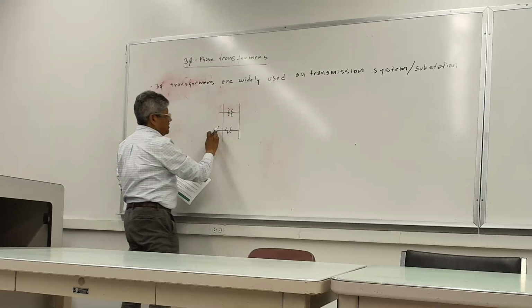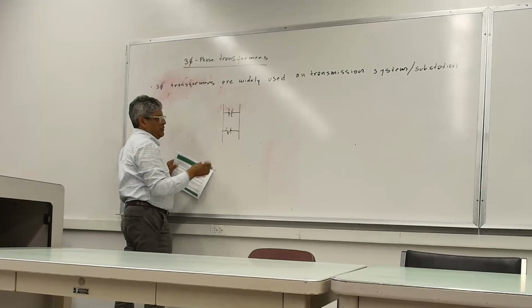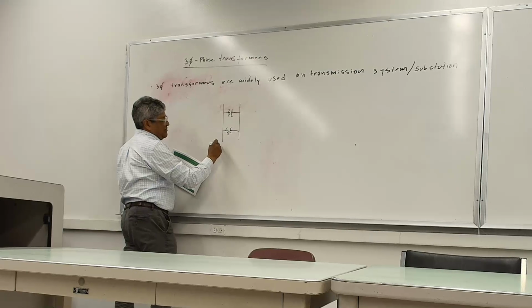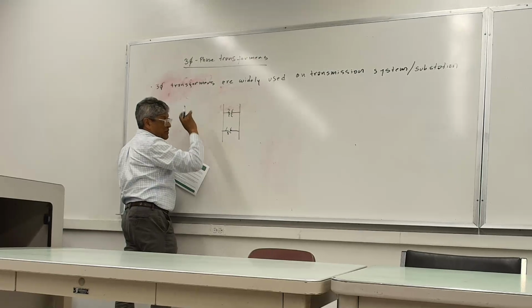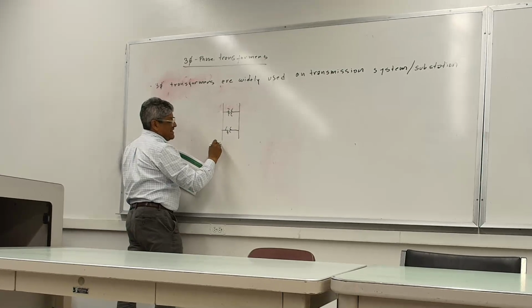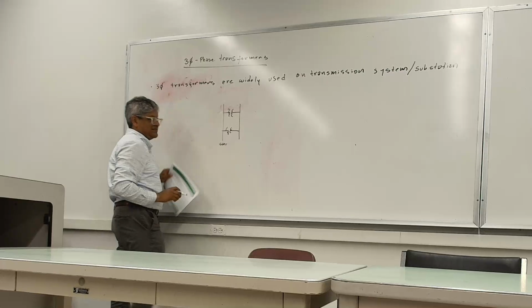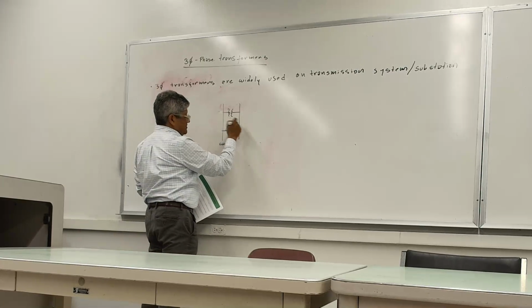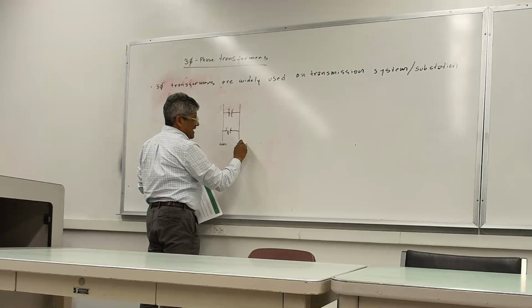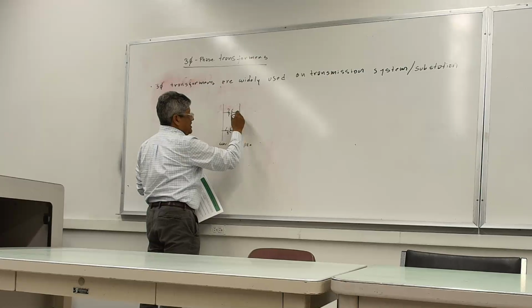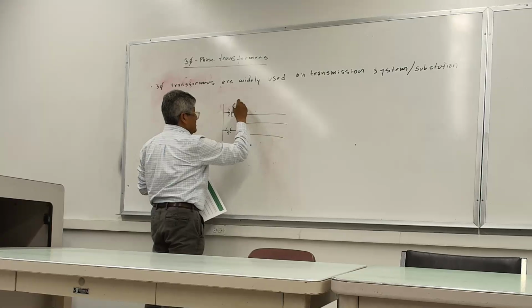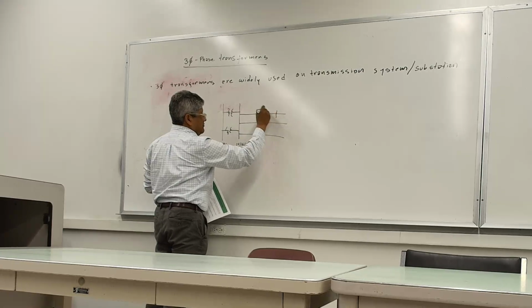Say, for instance, I'm going to use Edison as an example, but that can be PG&E, San Diego, can be any utility. In some companies they call it sub-transmission, some companies they just call it transmission. For instance, they can bring 66 kV, and they have the step-down transformer from 66 to maybe 12, 16, 18 kilovolts, and then they bring feeders out of the substation to serve the different customers, right?